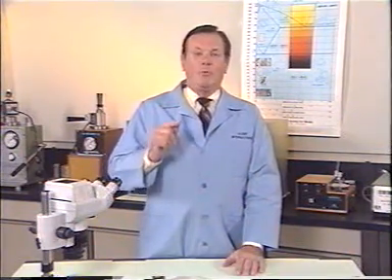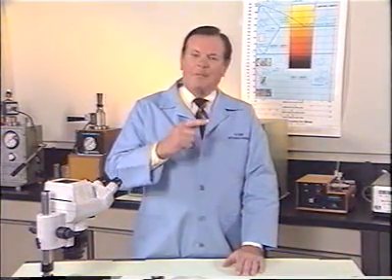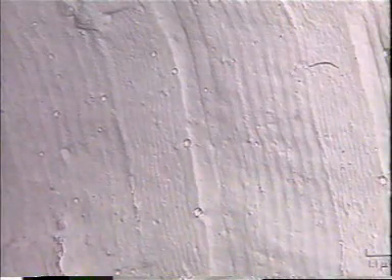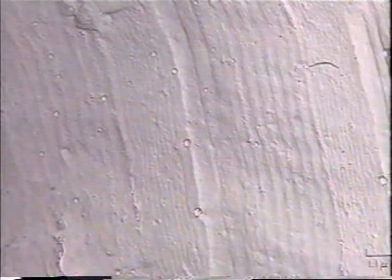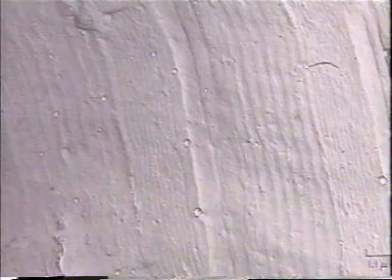In relatively ductile metals, each stress application high enough to cause a crack to grow forms a tiny ridge-like striation at the tip of the crack. These striations are frequently visible in electron microscope examination of the more ductile metals.